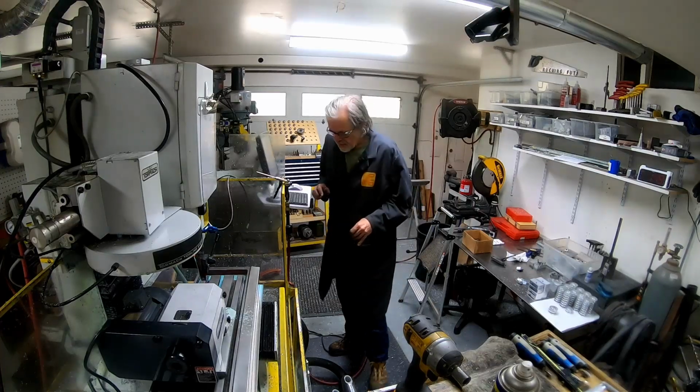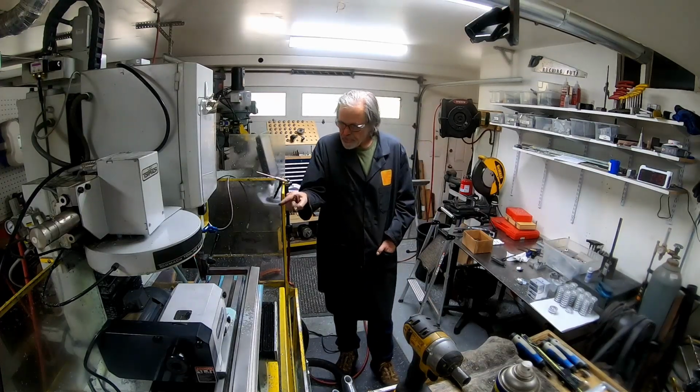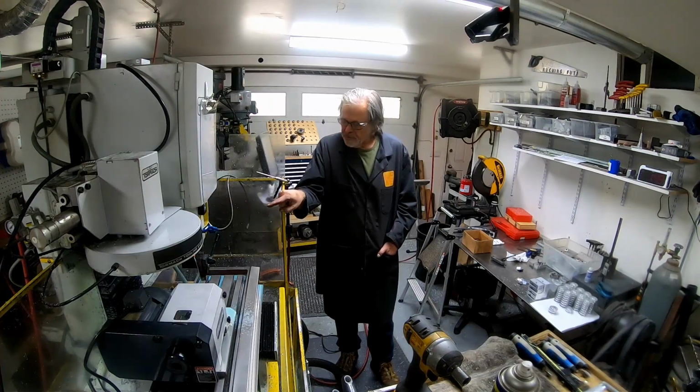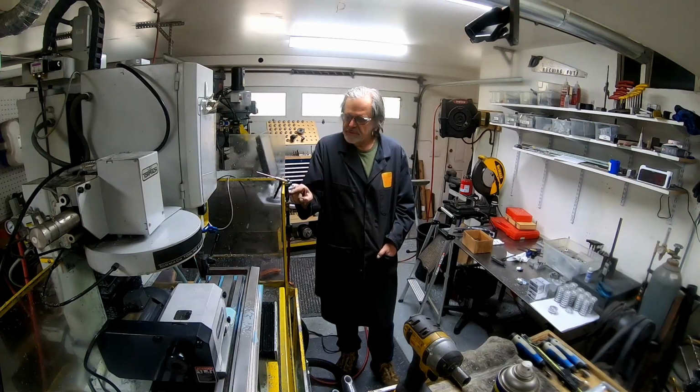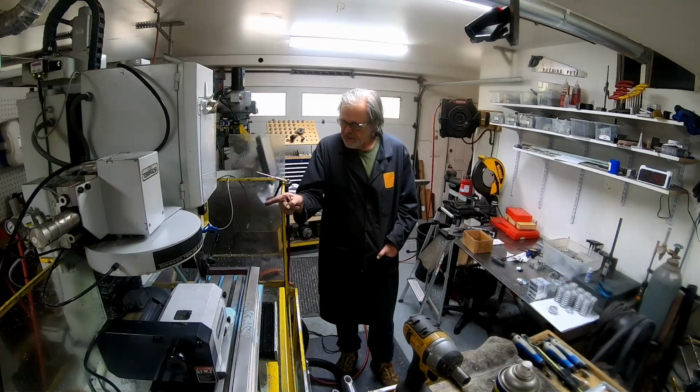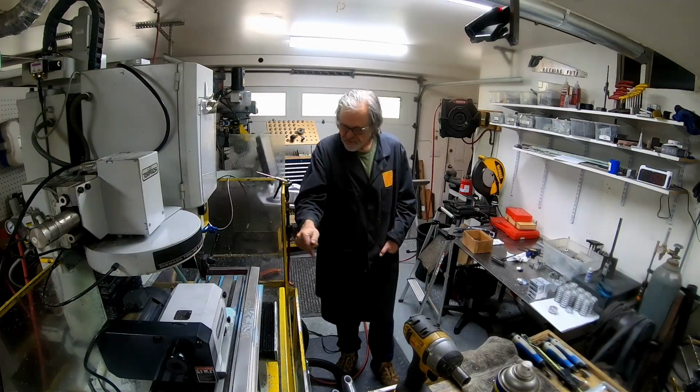That looks sane. The operation here, I'm going to be making a chamfer going up, going across to clean up the flat surface, then down to form an O-ring groove, then up and then back and then down again to widen the O-ring groove, because the O-ring groove is a bit larger than the width of that insert, then back up to diameter, back to the left, and then continue with the chamfer on the left.